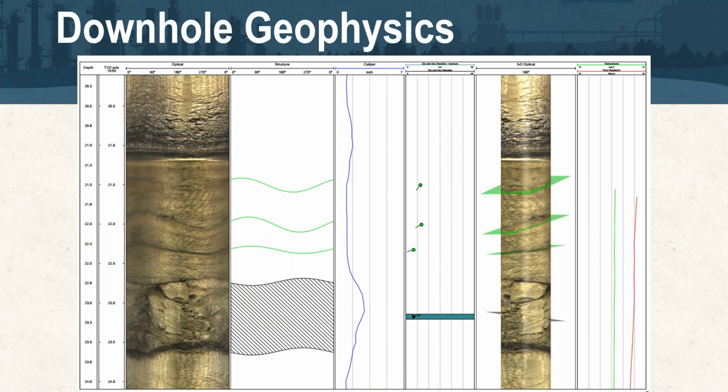And what we found that's really interesting and quite remarkable is that the injection tooling itself, or the injection methodology, cuts through the bentonite quite easily and can access those permeable zones within the formation that would otherwise be inaccessible, whether it be through traditional direct push due to early refusal, or off limits because the borehole integrity is too poor to be able to utilize packer assemblies like we've talked about here. Actually, we're utilizing this technique on a site currently this week down in South Central Tennessee, and doing a combination of overburden, straddle packer injection, and utilizing this pre-drill technique. So for the remediation side, this method works quite well.